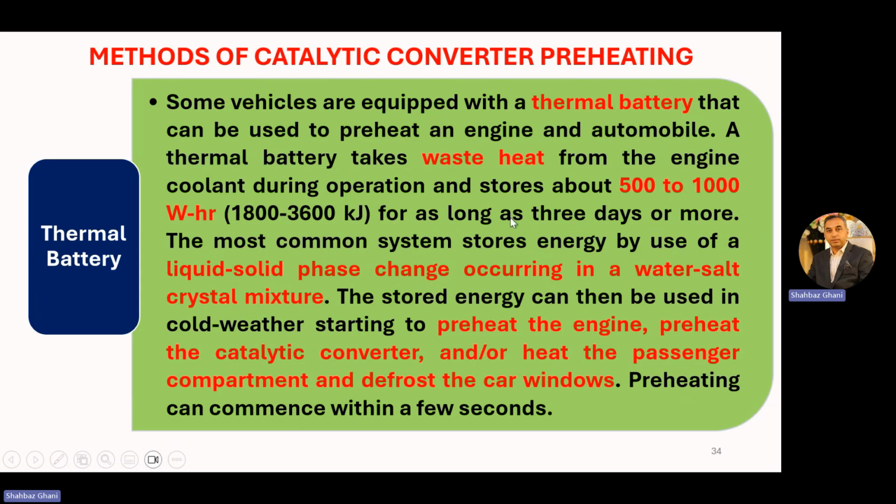The most common system stores energy by liquid solid phase change occurring in a water salt crystal mixture. The stored energy can then be used in cold weather starting to preheat the engine, preheat the catalytic converter, and or heat the passenger compartment and defrost the car windows. So that stored energy is used in all these functions. Preheating can commence within a few seconds.